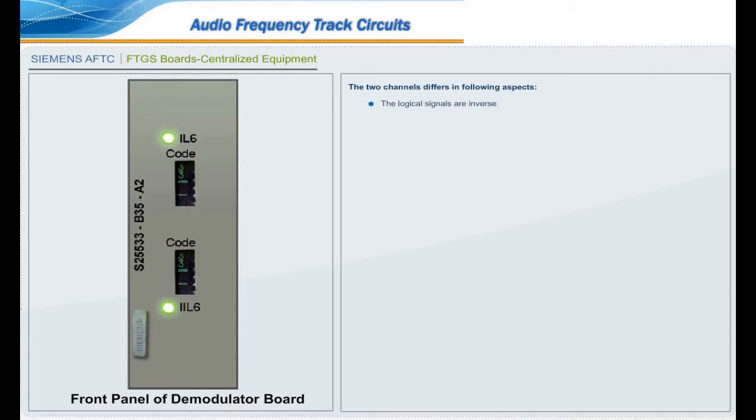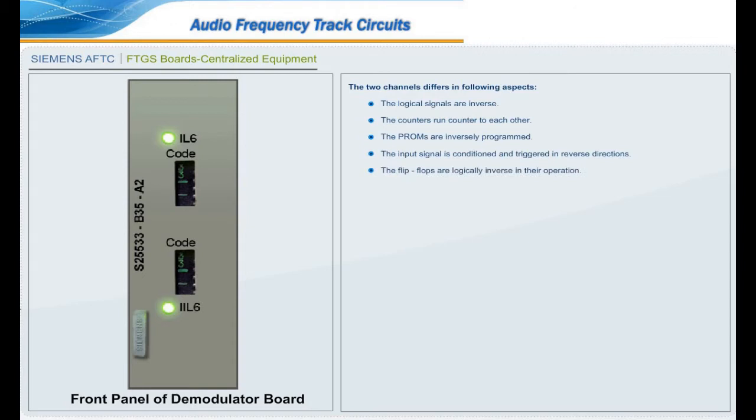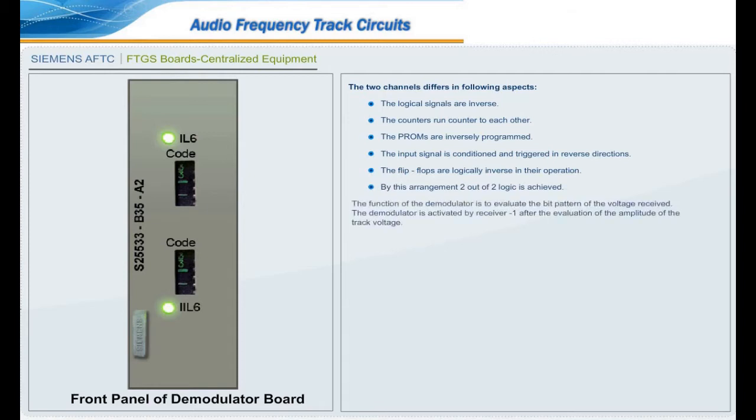The logical signals are inverse. The counters run counter to each other. The PROMs are inversely programmed. The input signal is conditioned and triggered in reverse directions. The flip-flops are logically inverse in their operation. By this arrangement, 2 out of 2 logic is achieved.